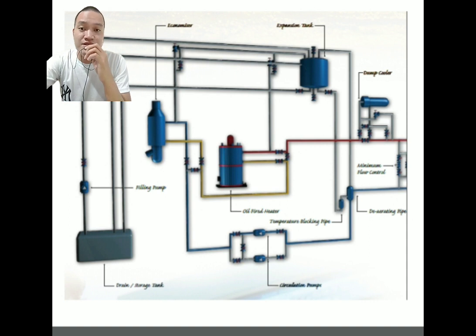Then the heat should be applied in 20 °F to 25 °F increments until the heat transfer fluid gets to a viscosity of 10 centipoise or less. So the reason for this is to ensure that you have a turbulent flow through the heater, where the heat transfer fluid can remove just as much heat as the heater can supply to the coil in the heater. And also there will be no thermal cracking of the oil.